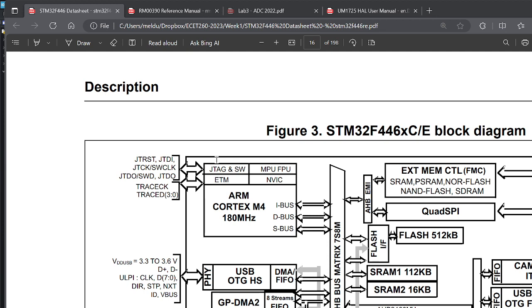For instance, in our addressing, 32 bits, we have 4 gig of address space that we can attach things to. And we'll have a look at the memory maps. But we could attach external flash, external static RAM, a TFT screen in that fashion as well. And you could put it in your memory map in a certain location and directly address it. And that's what all of this stuff is available for.